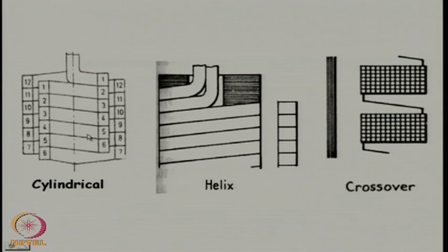The low voltage winding are usually made up of rectangular conductors. It may be a single conductor or a large number of strips taken together and wound on the insulating cylinder of the low voltage winding. Between turns, another set of duct and insulation will be provided, on which a second layer can be wound.